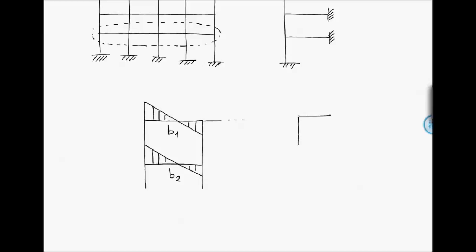we have that from the right we have TB1, which is the shear force for the beam B1 calculated with the cross method. Then, in order to determine the axial force on the column, we do it by considering the equilibrium, and we found N1 on the column, which is a compressive force.